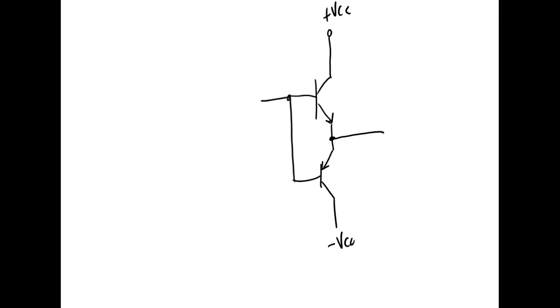We don't have to put a coupling capacitor out because this puts AC out. It doesn't put DC. It won't put AC superimposed on DC. It puts AC out. So I come over here. This goes positive. So right here, if I put no signal in, the output would be 0. All right, you understand that?